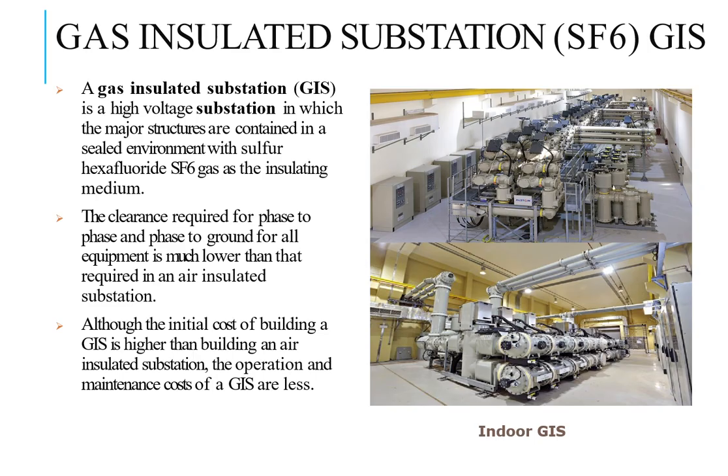The clearance required for phase to phase and phase to ground for all equipment is much lower than that required in an air-insulated substation, although the initial cost of building a gas-insulated substation is higher than building an air insulated substation. The operation and maintenance cost of a gas insulated substation are less.